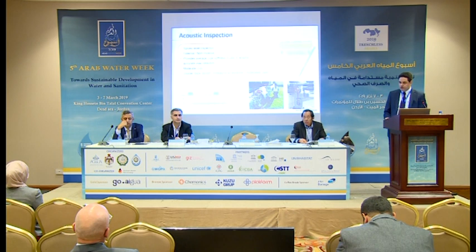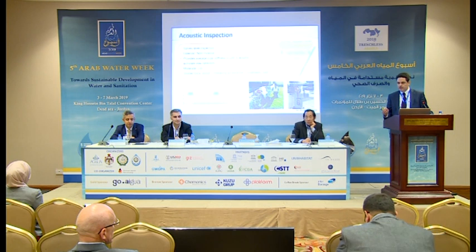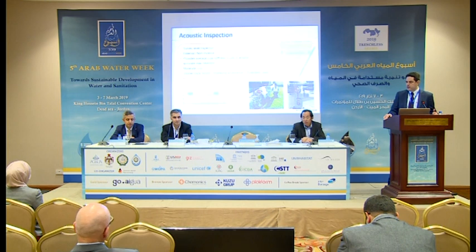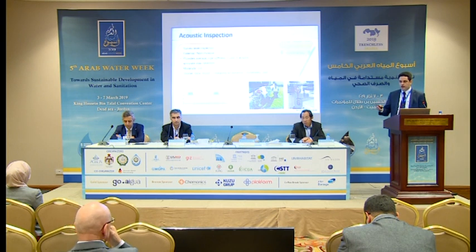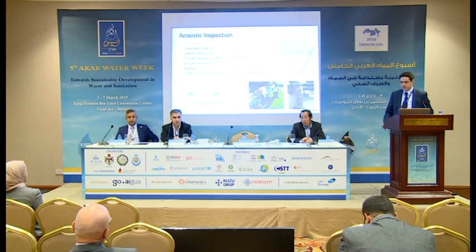The second inspection method is what we call the acoustic inspection method. This is one step up, basically, from the visual and sounding. It is referred to as a survey level inspection technique in general. The advantage is that it is a non-invasive technique. What it does is basically sensors are installed on existing pipeline features like hydrants or valves or something like that. Or if they don't exist, they prepare a pothole to allow access to the surface of the pipe to lower a sensor there. But the pipeline remains in service while you do that.